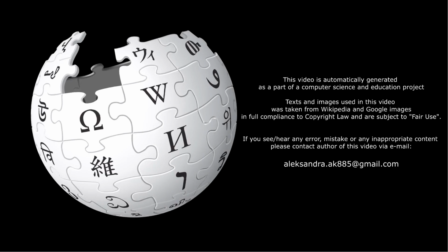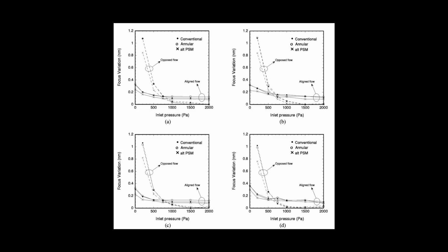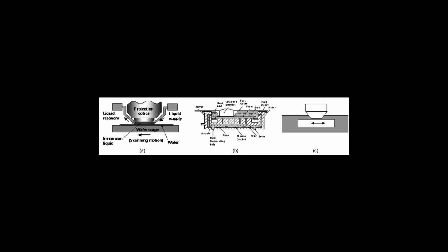Defects intrinsic to immersion lithography have been identified. Reducing particle generation due to the water dispensing unit was found to reduce the incidence of defects. Water also has been shown to extract acid from photoresist. Specifically, photoacid generators, PAGs, which produce acid upon radiation exposure, are extracted into the water. This must be managed to ensure the lens is not corroded by the acid or contaminated by the extracted agents, and the photoresist is not chemically altered to the point of being defective.